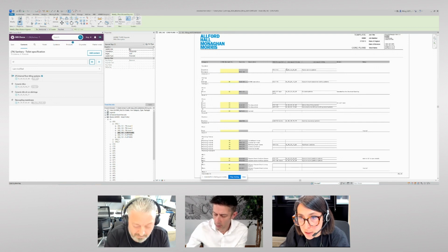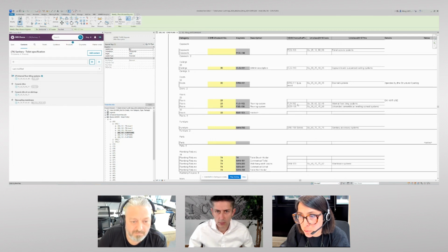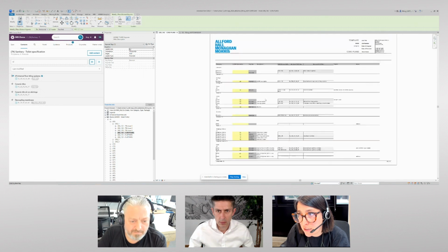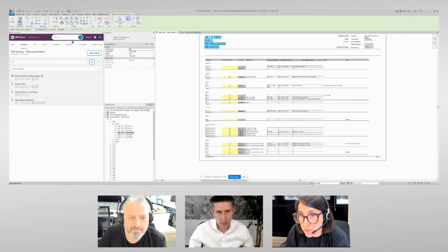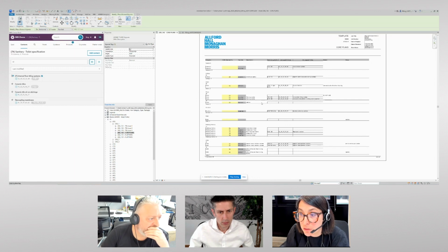associated to the model. And if I go down to floors, you'll see that floor 102, that's the keynote. That matches the suffix that we've brought in from NBS. That's the Uniclass code, and that's the Uniclass title. So we can use this in a similar way that we use the summary sheet from NBS. It's good to ensure that there's no discrepancy between the model and the specification. And we found the NBS plugin hugely helpful for doing this level of checking.